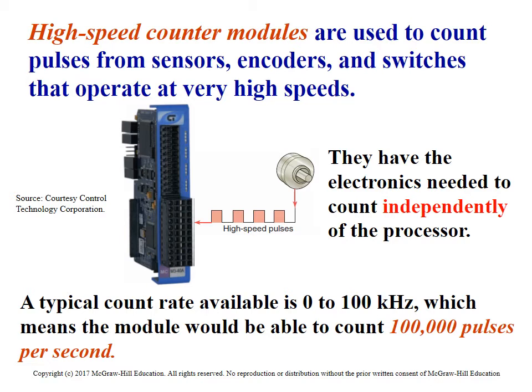Every time it scans that card, it just dumps that information right to the PLC. So the PLC comes back with, I'm at 10 counts, I'm at 20 counts, I'm at 30 counts, I'm at 40 counts. As it's continuously counting, it's capturing every count, not missing a beat. It works pretty darn good.